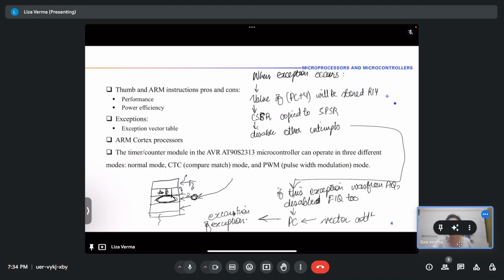It will start from somewhere in the middle of the ISR of the first exception. So to prevent that, we write some jump conditions here. But for FIQ, we do not need jump conditions because it has ample space, and you can write however long your ISR is.